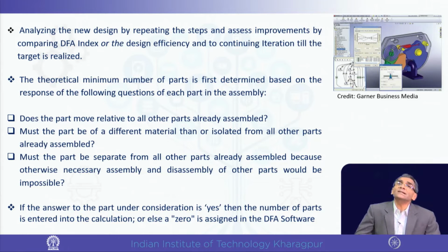Second, if the material is not the same, then it has to be 2 different parts. If something is made of aluminum and something made of steel, then it cannot be one part. And third, for maintenance or repair purposes, if they are to be separated, then they cannot be one part. Other than that, the rest are all candidates for consideration as a single part.